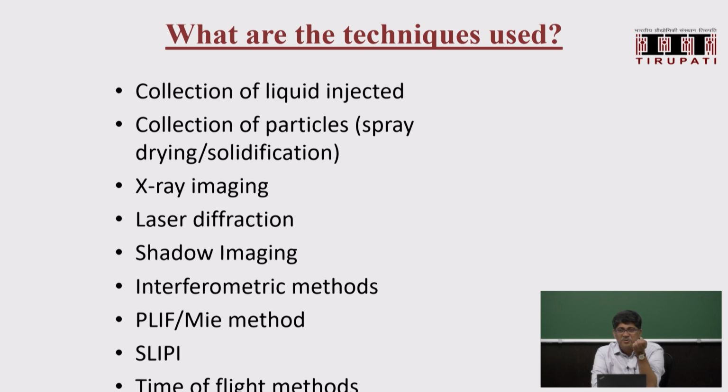Or earlier, before the laser diagnostics, people used to take any kind of spray and freeze it. You create a very low temperature, freeze it, collect those solid drops, measure them under the microscope, and you get the size distribution.